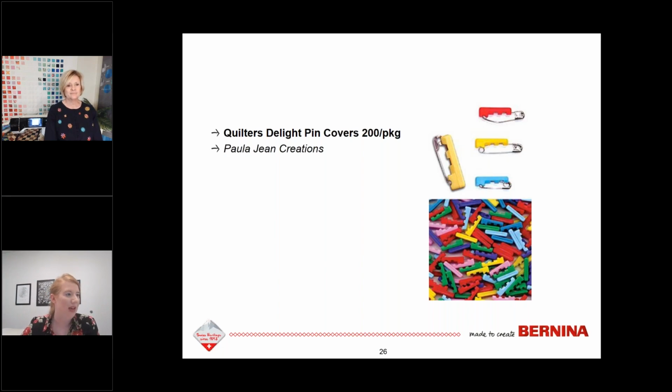Okay. How many stitches will the Smart Secure feature stitch at the beginning and the end? When I take it very, very slow, it's 3 stitches. But the sequence in which they're stitching, this invisible secure, it detects the direction that it's going to stitch next, and so it will stitch it in a way that it covers that securing stitch, and that's what helps make it invisible.